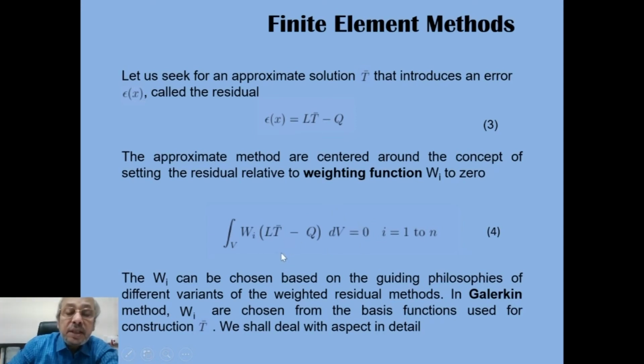That means it minimizes the residual and elevates T bar to T. That means T bar will evolve as the final solution T. And this weighting function has to be properly chosen so that what we ask for happens finally.